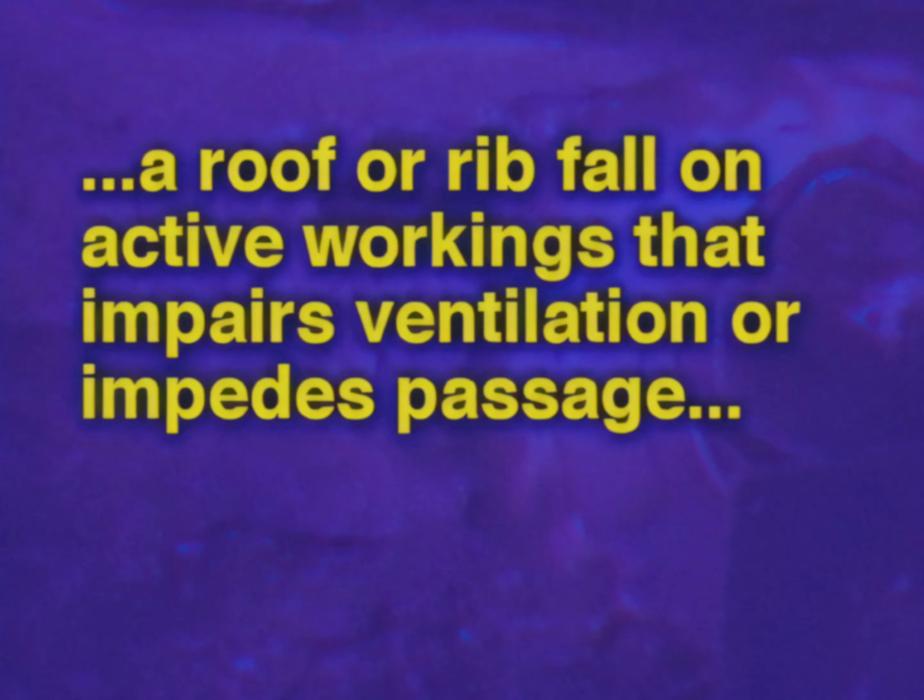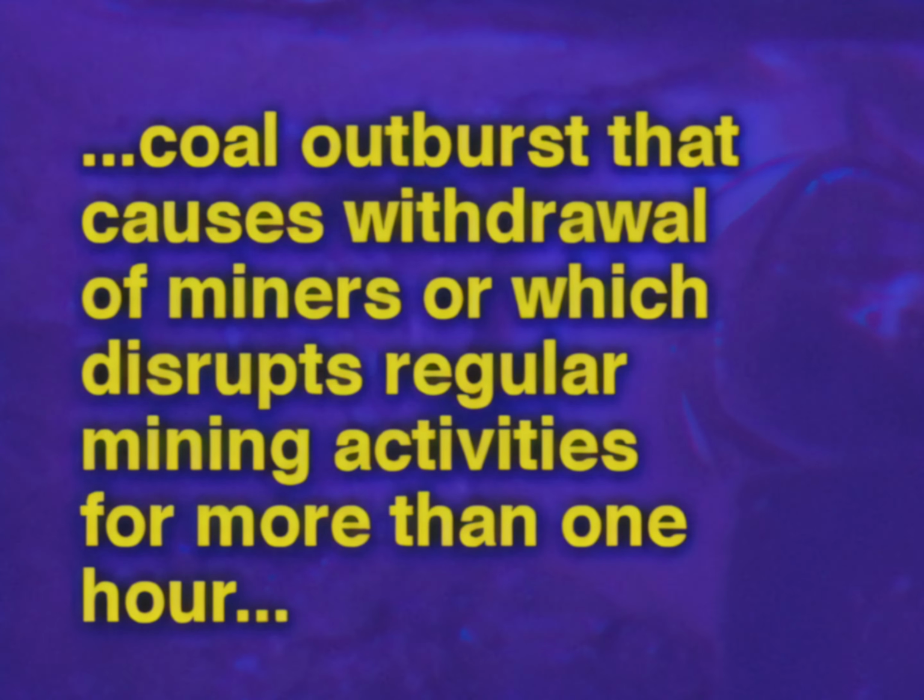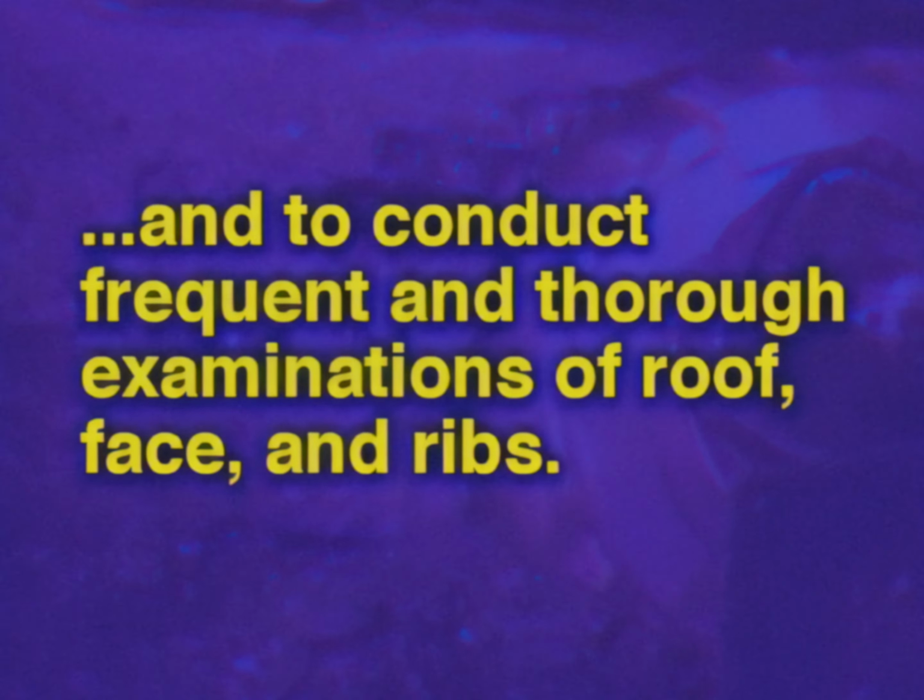A roof and rib fall on active workings that impairs ventilation or impedes passage. A coal outburst that causes withdrawal of miners or which disrupts regular mining activities for more than 1 hour. And conduct frequent and thorough examinations of roof, face, and ribs.